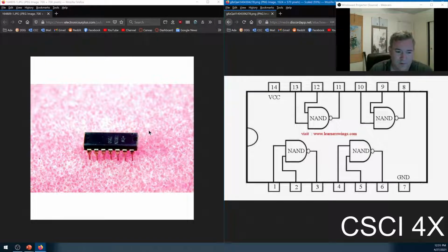Anyhow, this is how it works. Let's say that this is a 5-volt chip, just for the sake of argument. And you've got a Raspberry Pi, like this. The Raspberry Pi has these things called GPIO pins right here. Some of them are always on 5-volt output. That's high, that's true. Some of them are always on ground. There's a few special pins, but basically for about half these pins, you can control them in the software. So you write a program, and you can turn a pin on, and you can turn a pin off. And you can read the value from a pin.